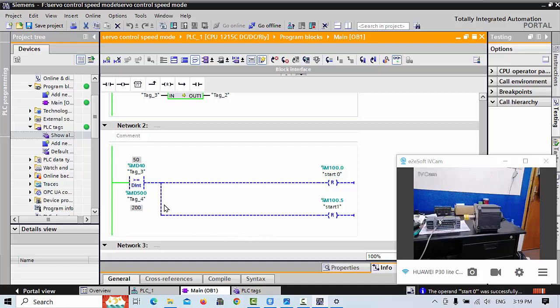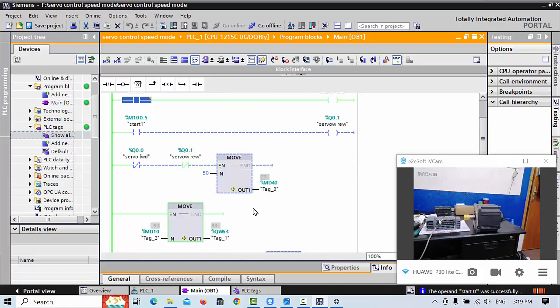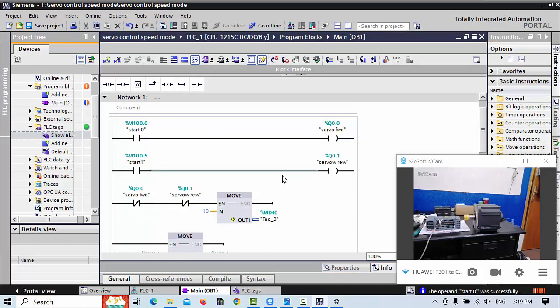Right? And also this set point will be working, and after this command works for this 50 speed, we will write it here 50. If you like to change this speed also, you like to start from 0, that is for 10 I think so, but 10 speed will not work because this 4 to 20 milliamps starts from 50 or 60.